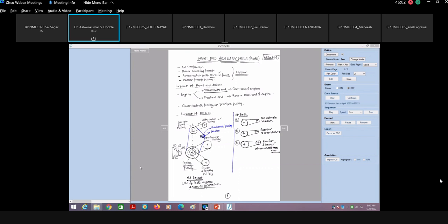Okay. Now, sir, when you fit the belt and you run the belt, a permanent set occurs, because you run the belt only when the proper tension is given to the belt. And once you give the tension to the belt, all the belts, even if they have run for one single rotation on the pulley, are called old belts. So there is nothing like a new belt.